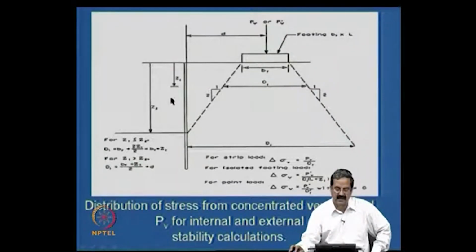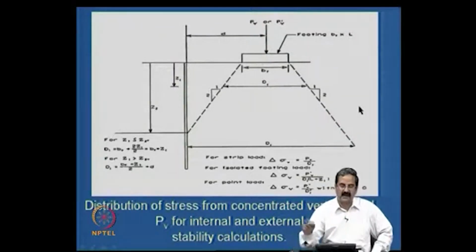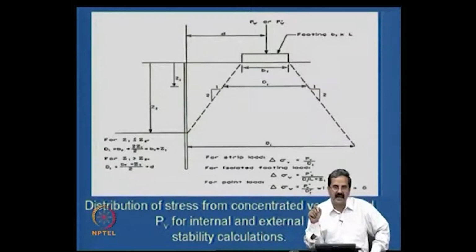You have to design the reinforcement properly, and we just saw that it's Ka times sigma V, right. How do you calculate the tensile force in the reinforcement? Essentially, what is the horizontal stress? You are calculating the tensile force over some spacing, and you need to essentially calculate horizontal stress.